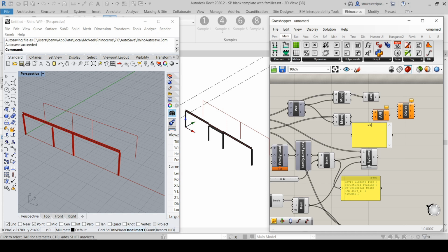I want to split up these spans into a number, which I'll put into a panel, which will be our maximum span of our decking if this was a composite structure. So I've got primaries along here, I'll have secondaries running this way, and the decking over the secondaries only has a maximum span of 2,800 or 2.8 meters, which is usually pretty safe for composite decking.